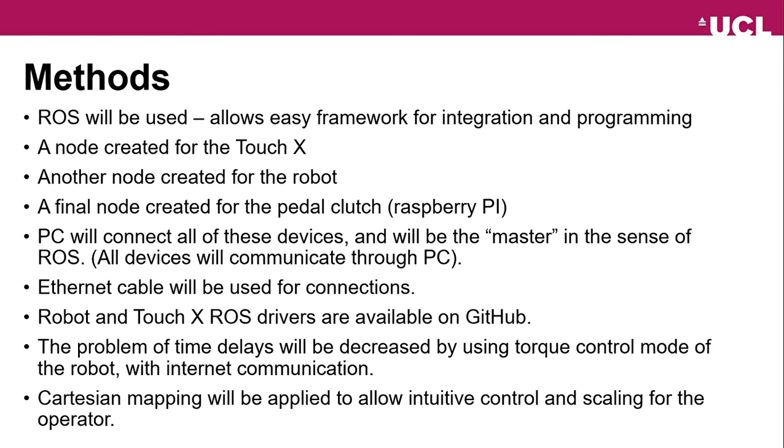For the connections, Ethernet cable will be used instead of the wireless connections due to some problems with the internet connection in the laboratory. Robot and TouchX ROS drivers are available on GitHub. The problem of time delays will be decreased by using torque control mode of the robot with internet communications. Cartesian mapping will be applied to allow intuitive control and scaling for the operator.